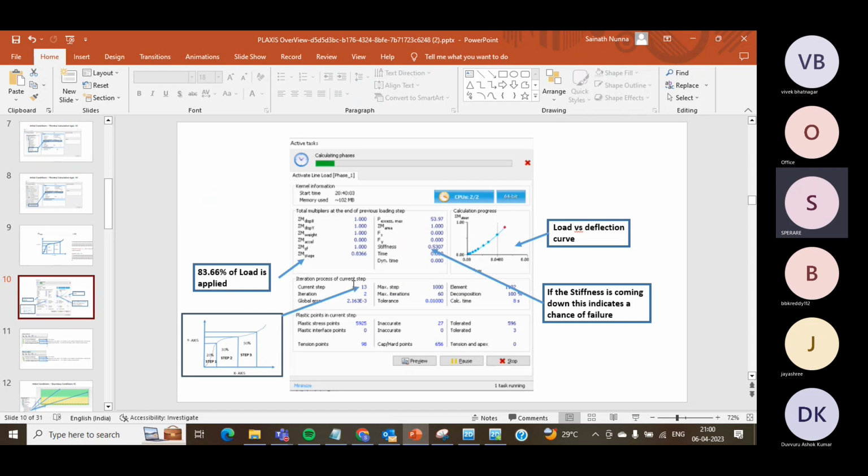So if someone sends you a screenshot, you have to see that if the sigma m weight here is 1, then they considered 100% density. But if sigma m weight is not 1, if it is like 0.7, then they consider only 70% of your density. So you have to go and question and check with them.